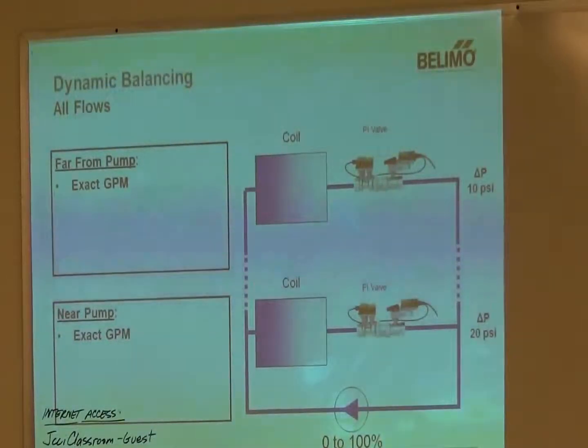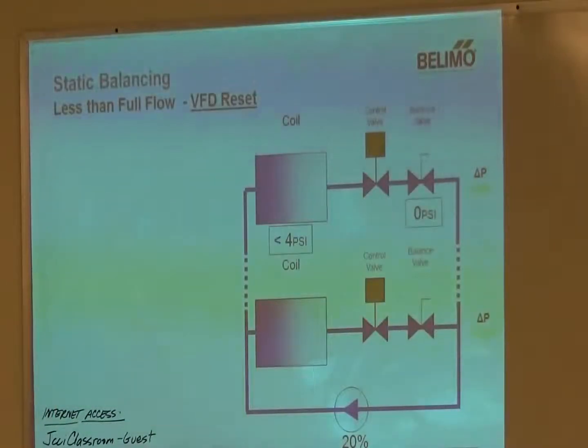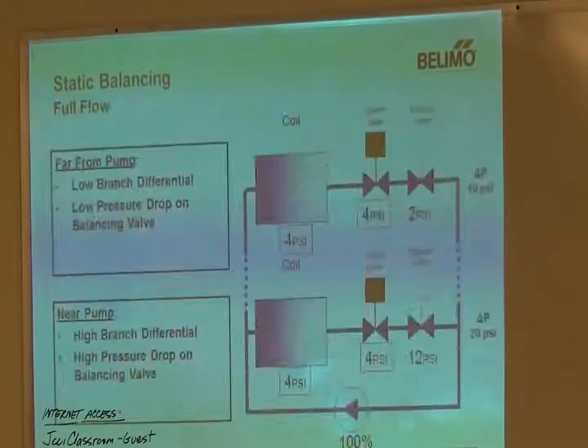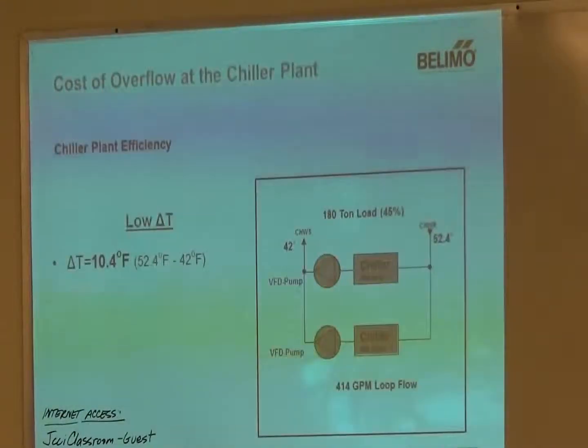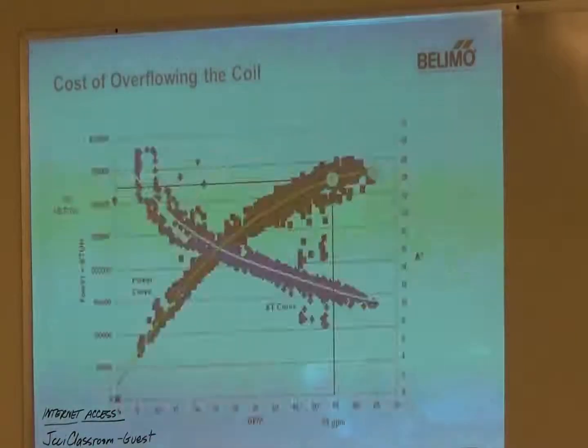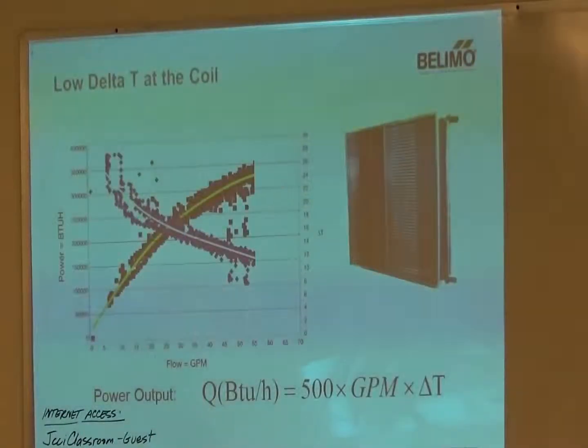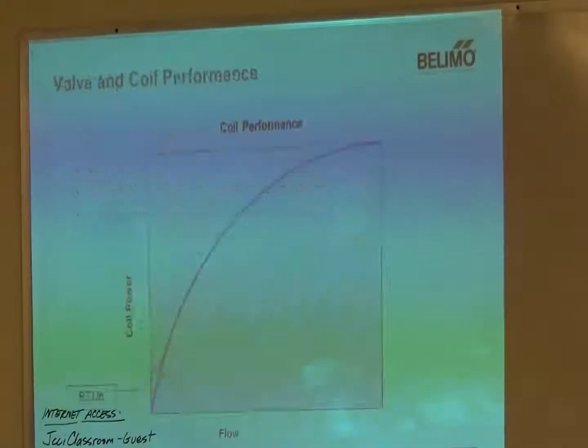Right. Now, yeah, let me just clarify a little bit. So we've been talking a little bit about two different types of pressure independent valves. I started out talking just pressure independent, or PICCV, and that was a mechanical pressure independent. Brian alluded to that a little earlier, whereas what we're talking about here is an electronic pressure independent valve, ones that have the flow sensors are electronic. With the mechanical, those ones can be ordered with their own taps.